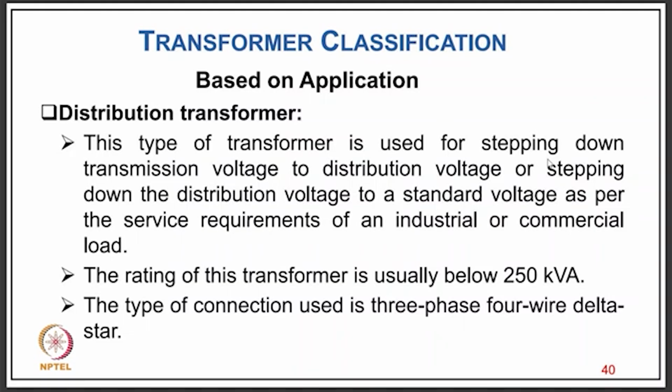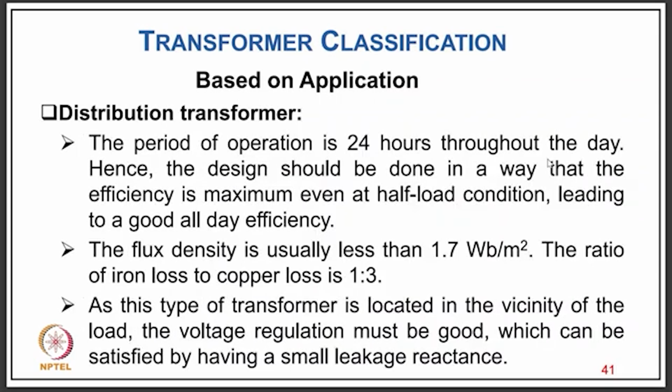single phase distribution. Because of this reason we have to keep the primary in delta. Otherwise, on the high voltage side we normally prefer to have a star connection, but here we have a delta connection so that it provides the path for the circulation of harmonic current, and that provides the stable neutral for the isolated secondary of the 4-wire system.